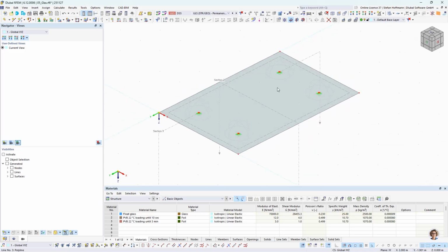What I would like to add is the function over here to add something to the selection or create a new selection. Usually you can, of course, mark the surface, hit the Control key, and add more objects into the selection. But if you are tired and do not want to do this, you can check this button and click objects once after each other. But this may cause trouble if you do not remember you activated it, because then a left click will not undo the selection. You have to click Escape.